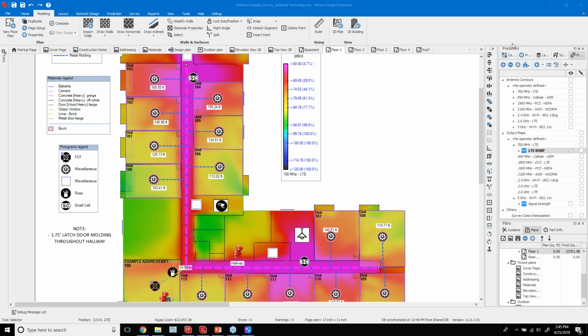Okay, that was actually a three-part question. So the second part is, how do you determine the number of strands of fiber for deployment? Yeah, so with the GPON network, we saw that we're deploying optical network splitters. That would potentially change the amount of fiber you need in your F1 segment, your F2 segment, F3. Standard for a GPON network is a 1x32 split. So from that splitter location, it's a 1-to-1 fiber ratio for GPON.